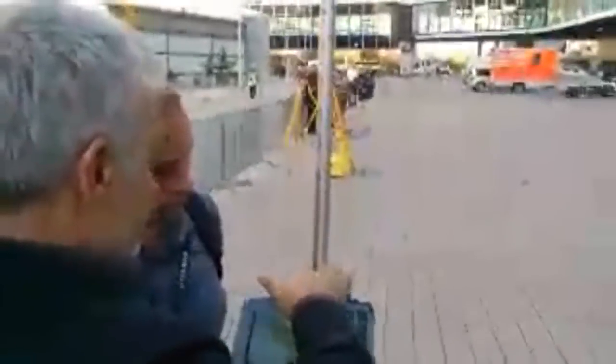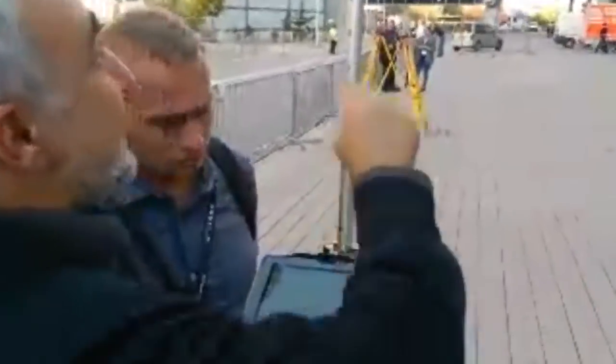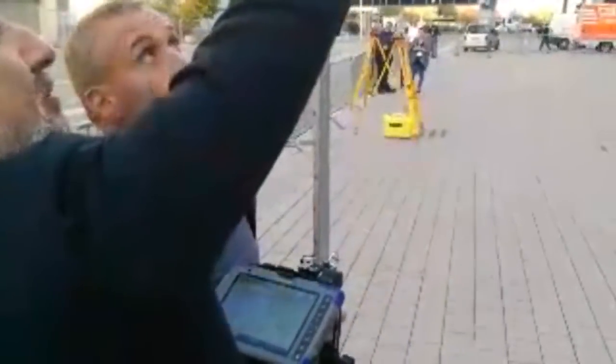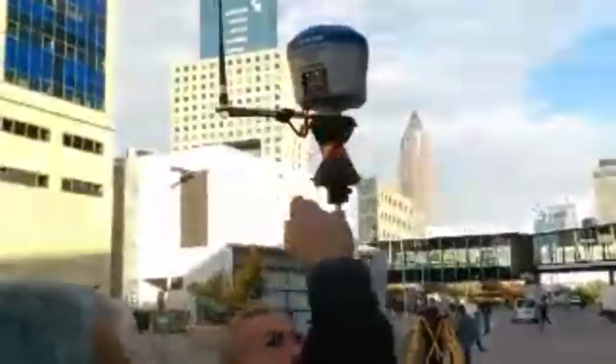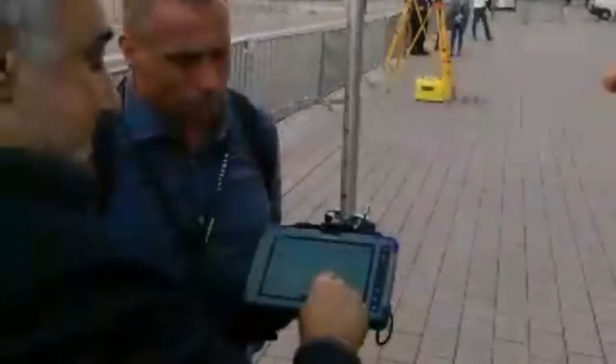I keep on going with the wizard. Go next. It is telling me to measure the height. I know with this pole, this is a good height, 198 something for the prism. And I added 62 millimeters. That is the distance between the center of the prism and the reference point of the antenna. So that is what this height is.